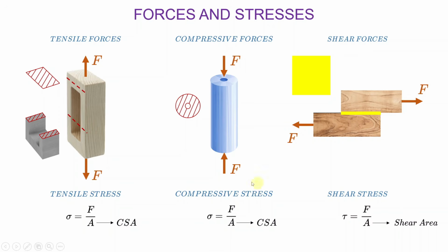The tensile stress and the compressive stress are often referred to as direct stresses. So if you come across the expression direct stress, it is referring either to the tensile stress or the compressive stress.